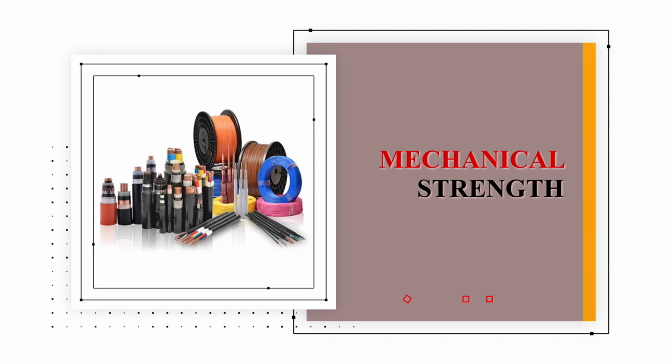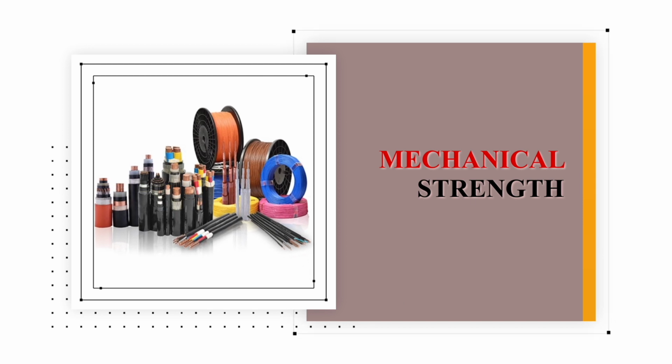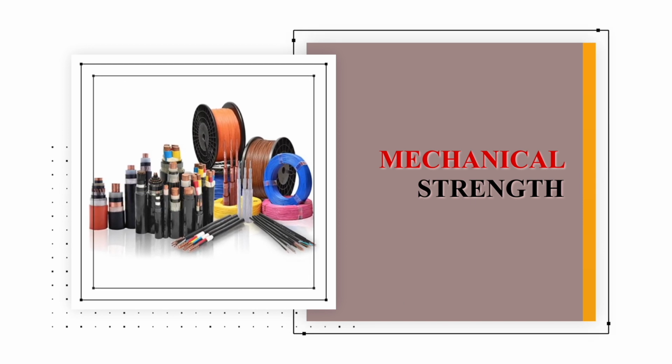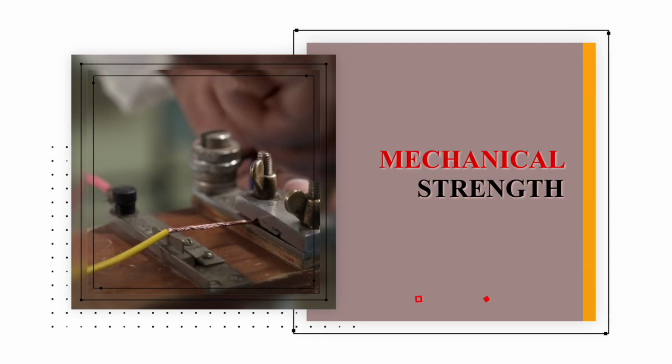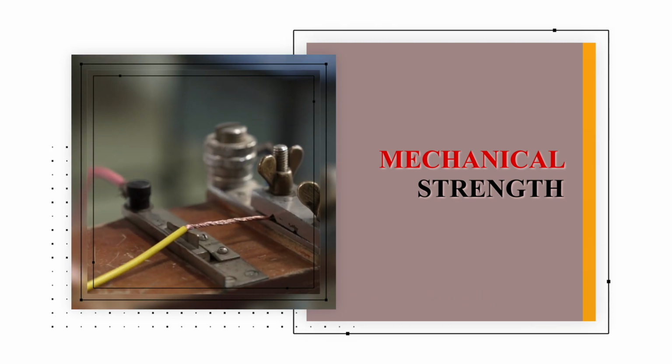Another important product which is essential for making electrical connection is cables or conductors, which come in different ratings and sizes for different purposes. So, what comes to your mind when we talk about cables, conductors and their properties like conductance, resistance, etc.? You all may be familiar with Wheatstone bridge and Kelvin bridge. These bridges are used for measuring resistance of cables and conductors.